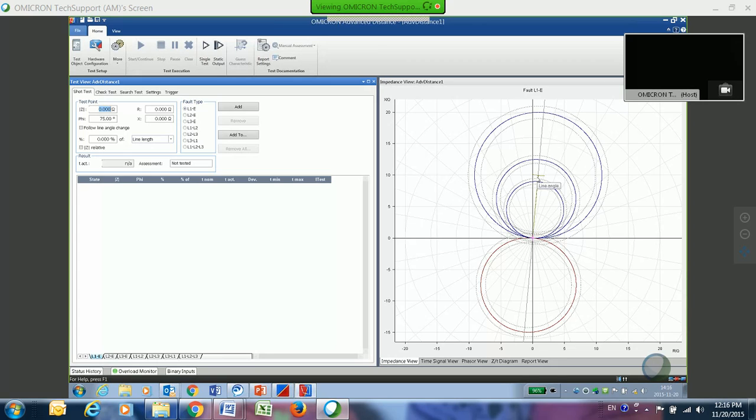Also note reach here. This is just a line that's been across here, so I can see zone 1 is actually less than my reach for that transmission line. Zone 2 is overreaching, and zone 3 is going to be even further out, and then zone 4 is going to be a reverse looking zone, as we showed you earlier. And that pretty much sets up everything here.